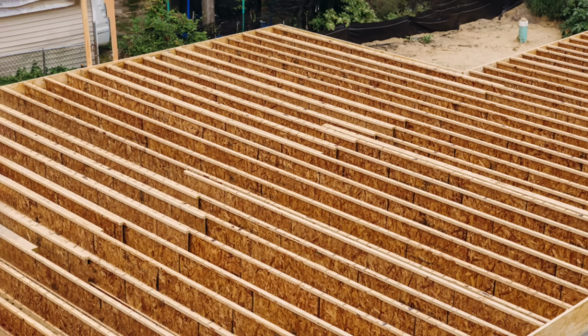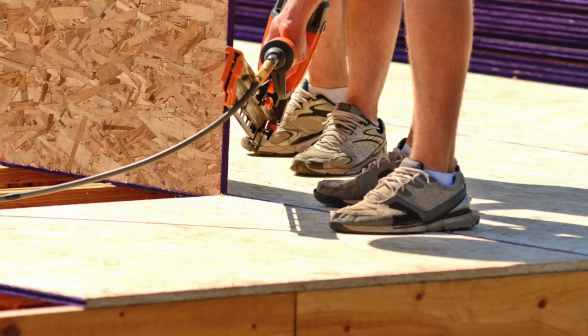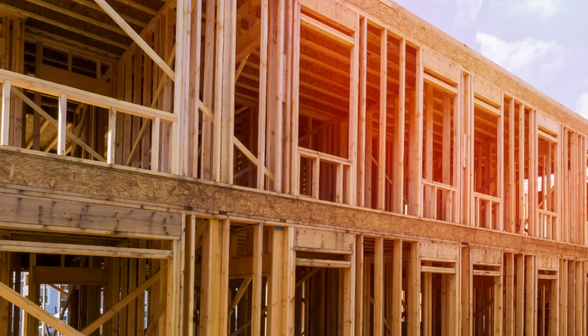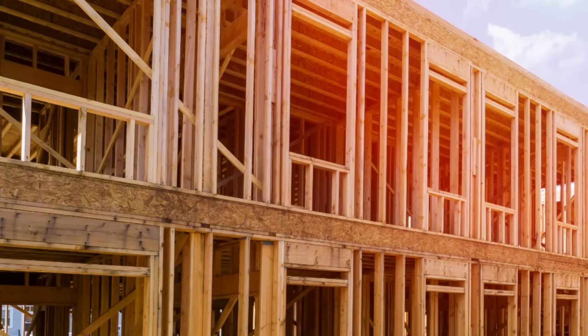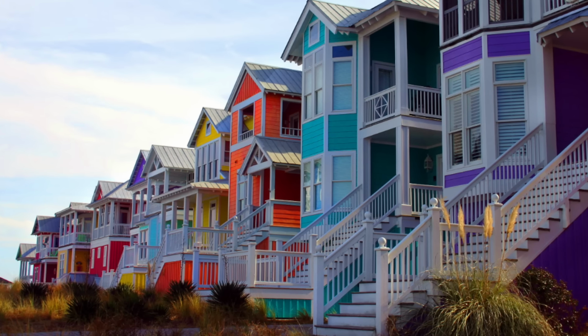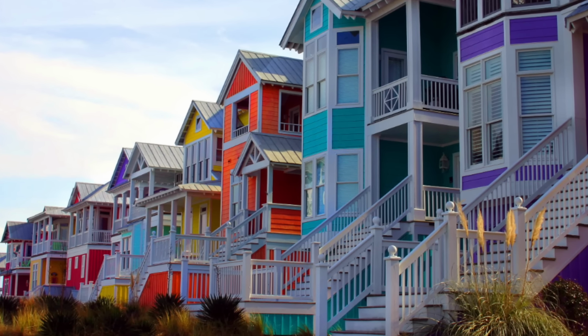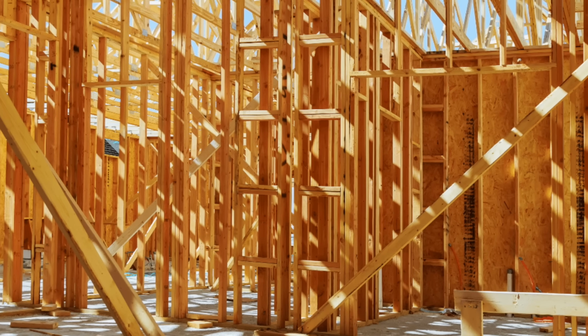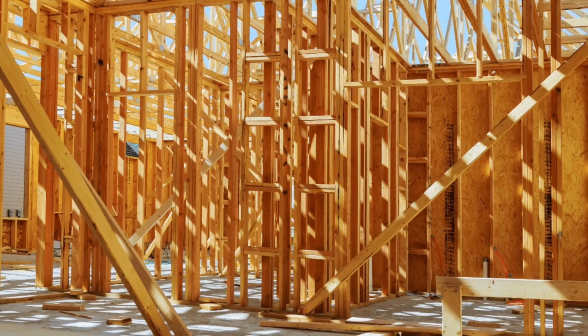Okay, continuing upward. Higher floors in a house are built much like the first floor. Joists sit on the top plate of the wall below. Subfloor covers those joists, and the next frame wall sits directly on that subfloor. It's pretty much exactly the same floor to floor. Taller houses may require more beefed up framing, especially on the bottom floor. But terminology-wise, words are going to have the same meaning everywhere. Things only get different again when you finally get to the roof.